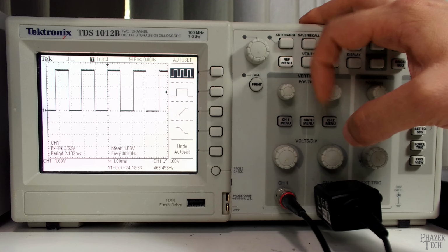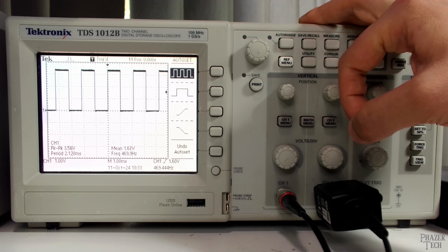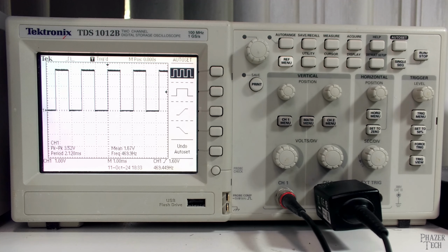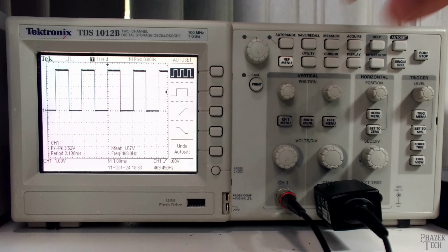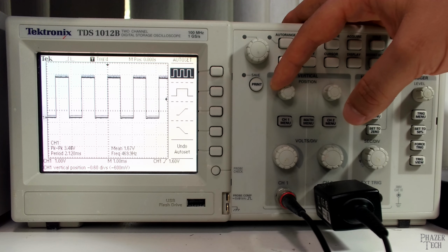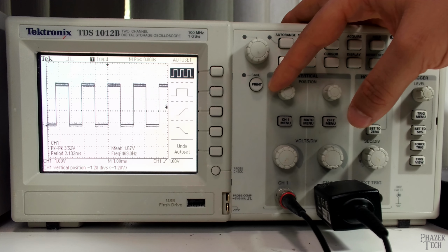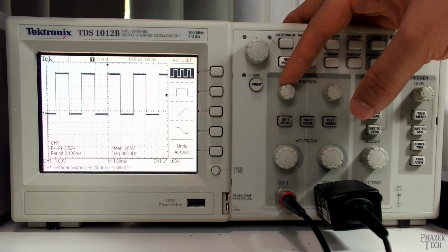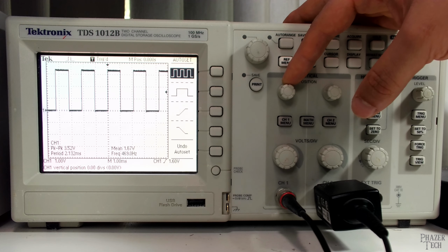And actually, for example, if you're dealing with a biased audio signal, so if we were to look back at some of my previous videos, I explained using resistors to bias an AC signal so that it works with DC components. Well, in cases like that, you might want to reduce the vertical position down so that your bias is sitting in the middle. But we're not dealing with that right now, so yeah.